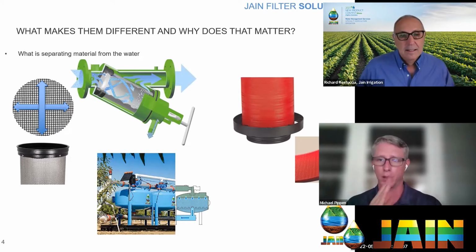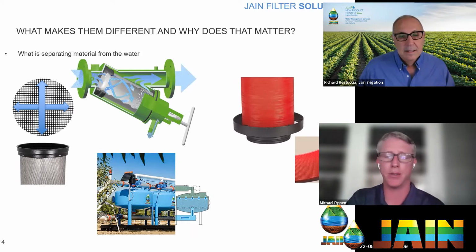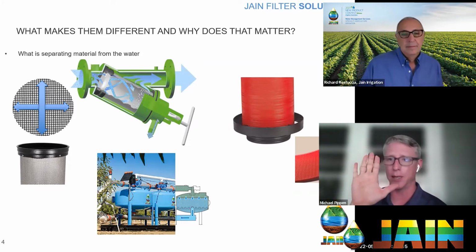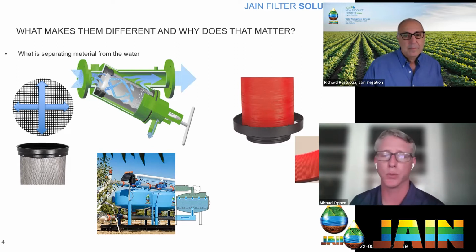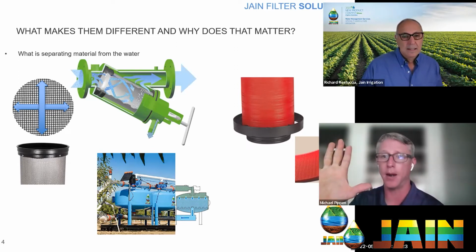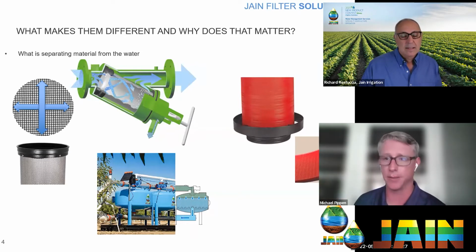A screen filter really works on these two dimensions, right? You've got a left, right, and an up, down. It is just like a screen on your front porch, like we said before. So there's really not a depth to it. It's kind of one line of defense. This works really well with inorganic materials like sand. It can catch it right there. And then, like we said, we can turn on that cyclonic action. That sand will release and flush out. Works really well in those applications.